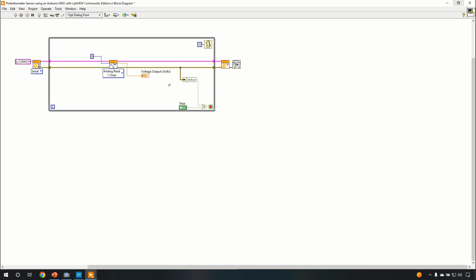We don't want to put too much demand on our CPU by running our while loop really, really fast. And you can monitor this using the index i right here of the loop. If we remove this timer, we can see that this index will increase exponentially. However, if we put a timer here, we can see that it slows down, which means it consumes less computational power from our CPU.